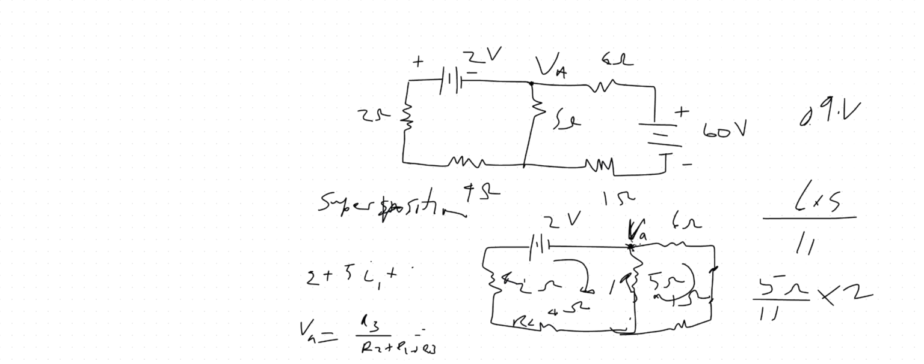And then that's how you plug that in and you multiply that by the 2 volts. And then that gives you 0.91. Now you'd have to do the same thing, this time with the 60 volt source though, right? You'd have to turn off the 2-volt source and turn on the 60-volt source. So you're gonna have to short circuit this next time.